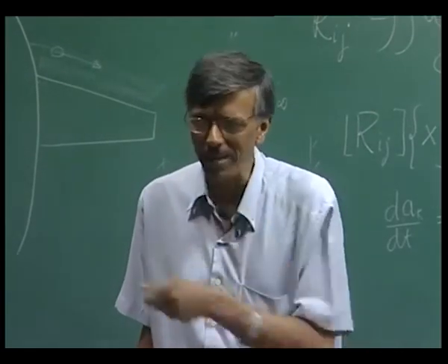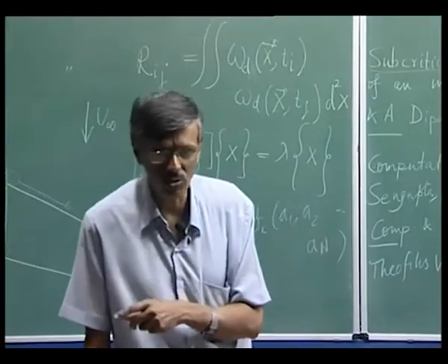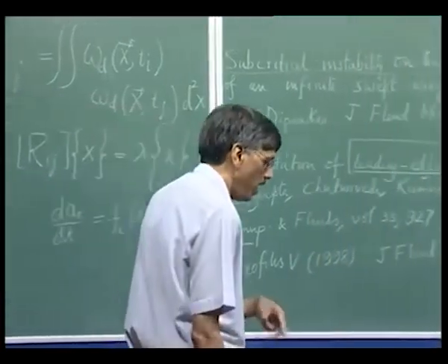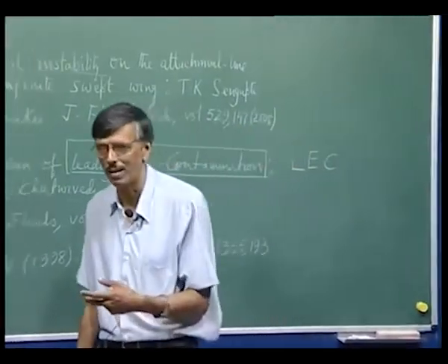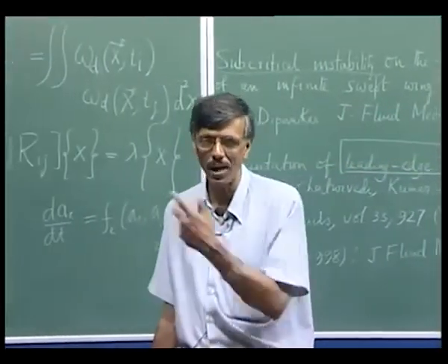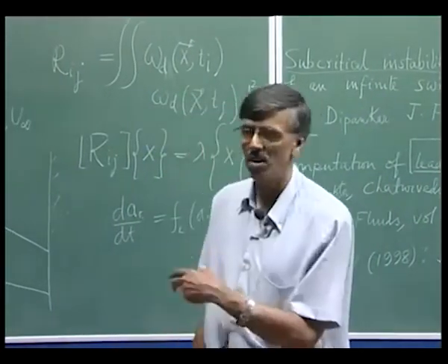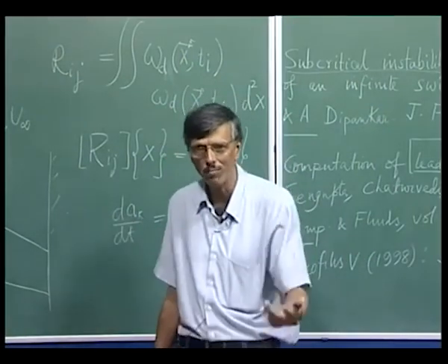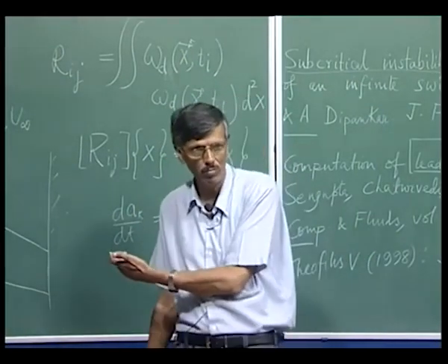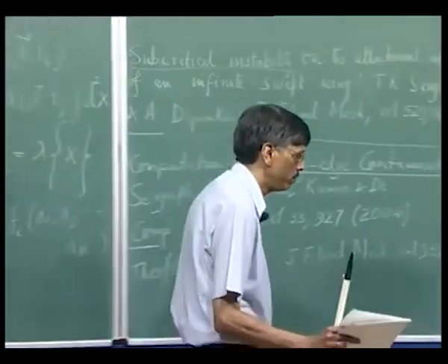This predominantly happens if your sweep angle is more than 20 degrees. So many a time you will hear people say that if we do not have a sweep angle less than 20 degrees, then we have 3D instabilities. So less than 20 degrees, you have a transition going from 2D stagnation point flow to attachment line flow. Okay? So this is something that we must remember.